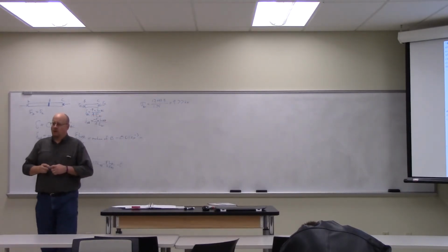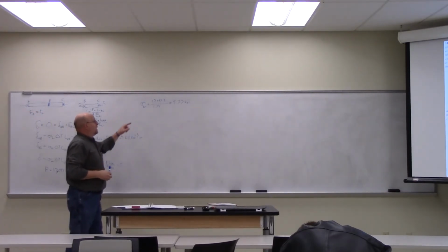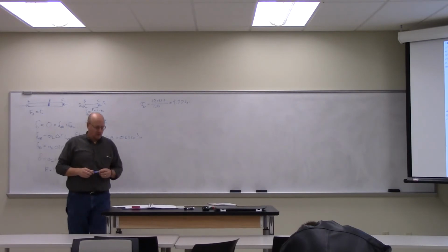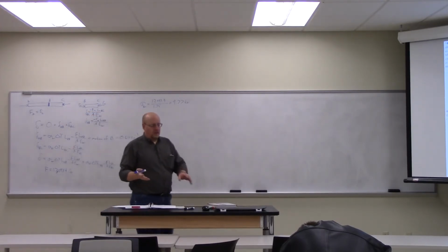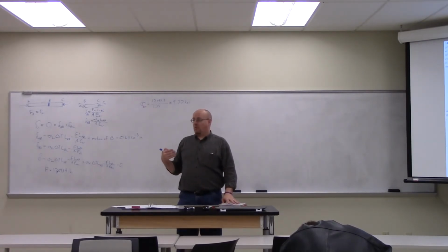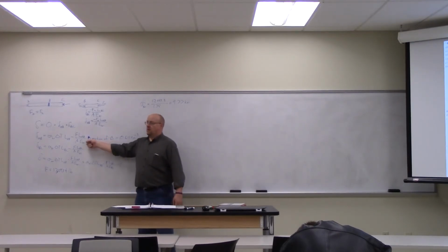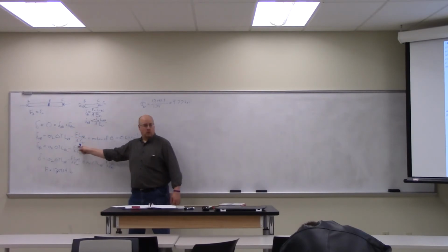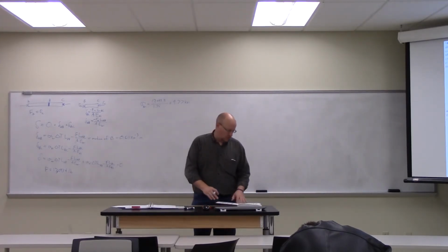You're right. Now, the thing I was going to say is you want to go back and check and make sure that that is less than the yield strength, the yield stress, of each of the two pieces. Because if it's more than the yield stress, then it's no longer behaving elastically, and so we're actually not going to be able to do this. This assumes we're in the elastic regime. The elastic modulus, that's why we're using Young's modulus. So you have to go back and check the yield strength on those two materials.